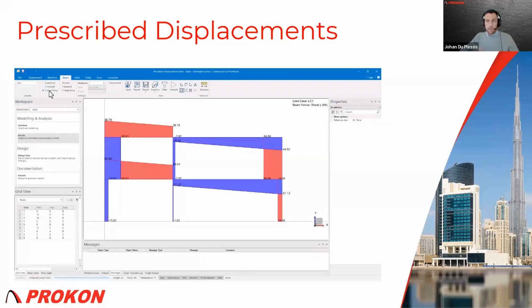In the absence of any other loads besides the self weight, we've got quite significant forces and stresses in the model, just because of that one column subsiding by 20 millimeters. So this is definitely something that you can use if you're looking at buildings or issues in construction, and you want to investigate what influence they have on the model.